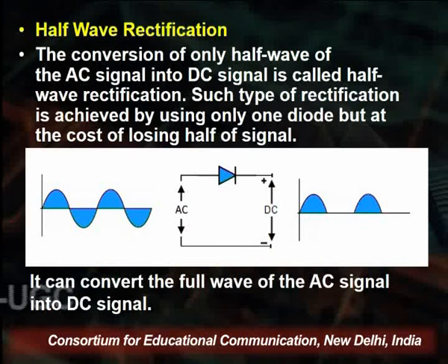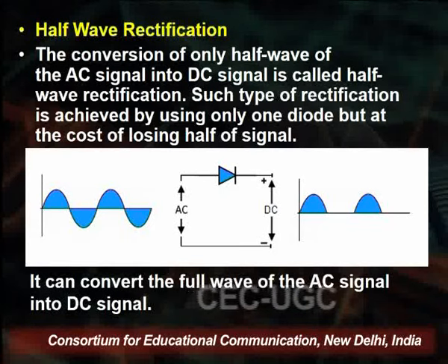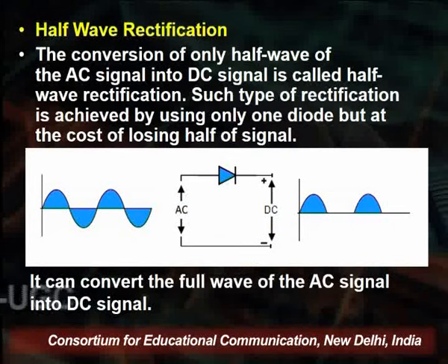So here we see rectification, where we use the diode. You see here in the diagram that this is a half wave rectification where we use a diode. This is the full wave rectification, where you see that 4 diodes are attached here, while in the half wave rectification only 1 diode is used. Basic applications of the diode: any circuit without a diode is nothing.